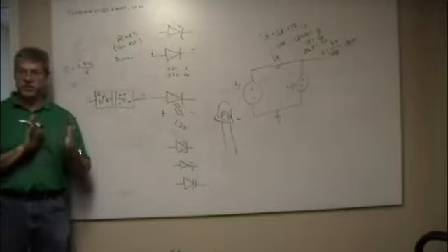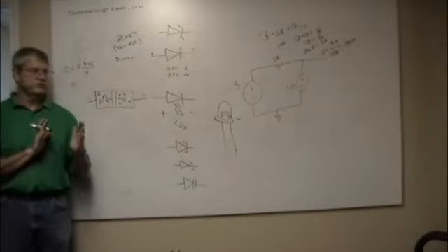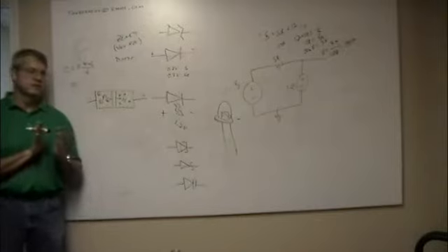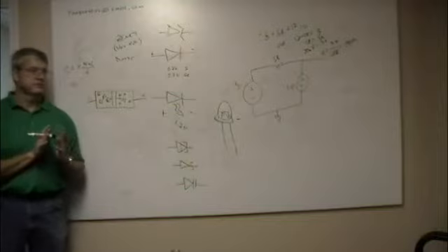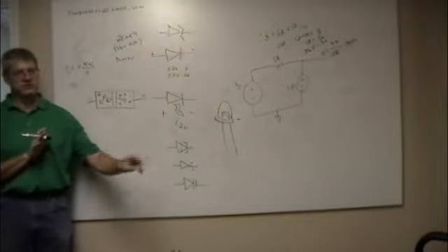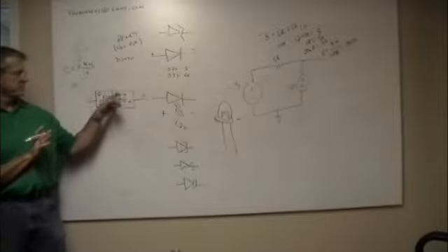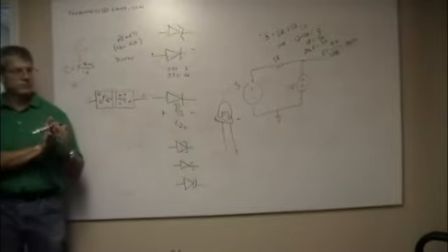And it's not a big change, but this is how, I don't know if that's what they still do, but it's how they used to make voltage controlled oscillators. So if you wanted to tune from 5 megahertz to 10 megahertz, you were changing a little voltage out there that was causing the diode to move out.